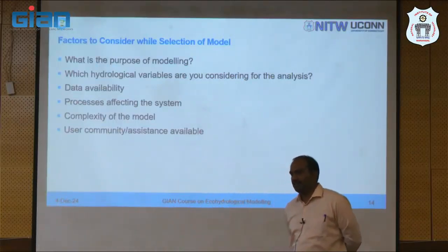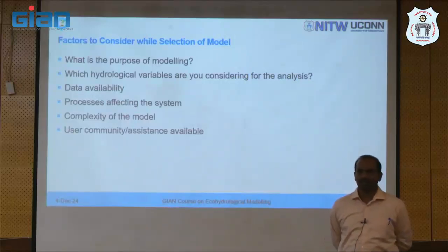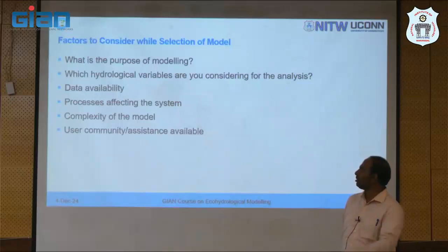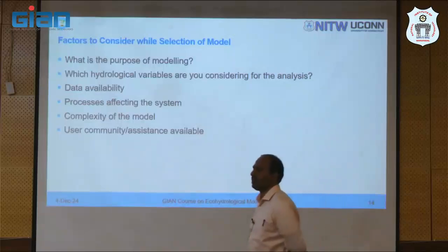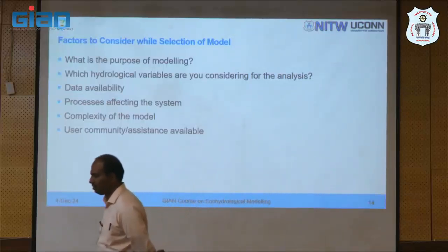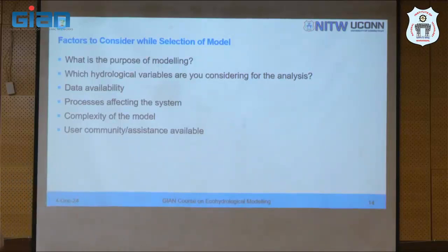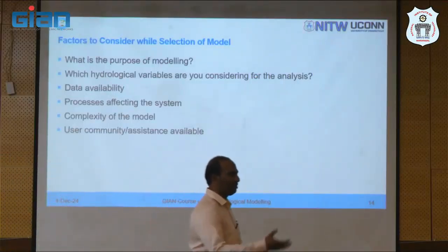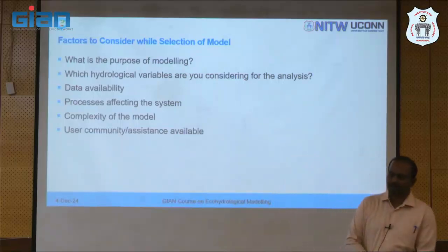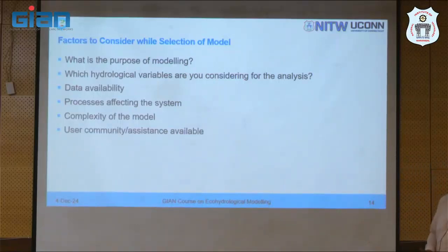But if you are only interested in flood modeling, then probably not. So the purpose of modeling becomes important, right? Or if you want to see how much is the reservoir inflow, then probably SWAT is not a good model. But if you want to see how your irrigation practices affect crop growth, still it's not a good model. You have to go for a crop growth model, right? If you are only interested in how irrigation is affecting crop growth, probably go for a crop growth simulation model and it will do your job.